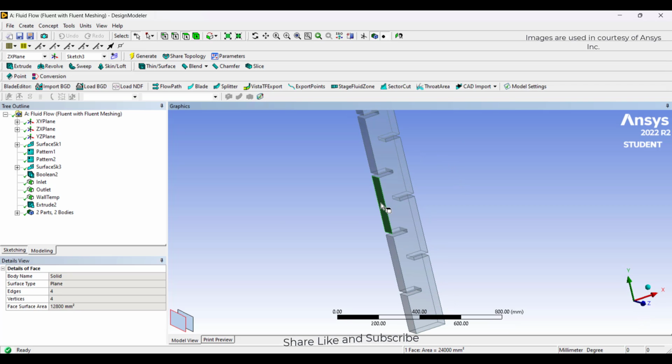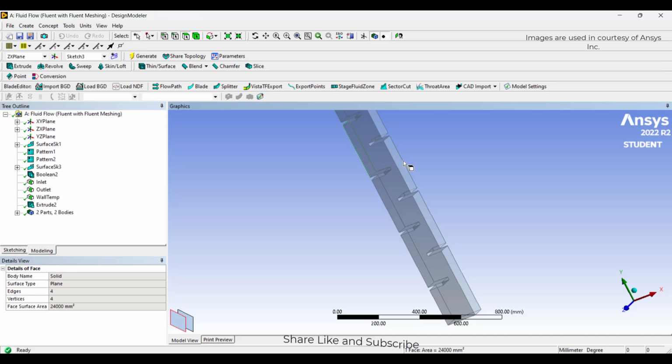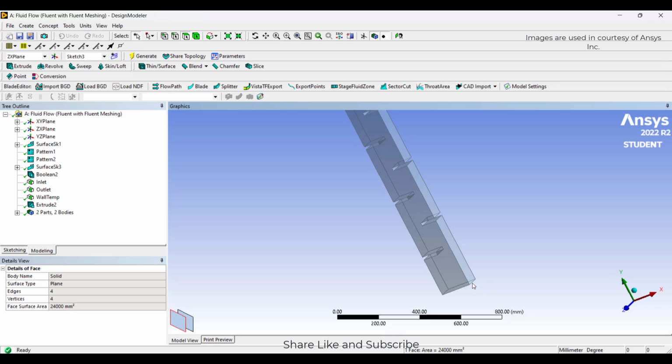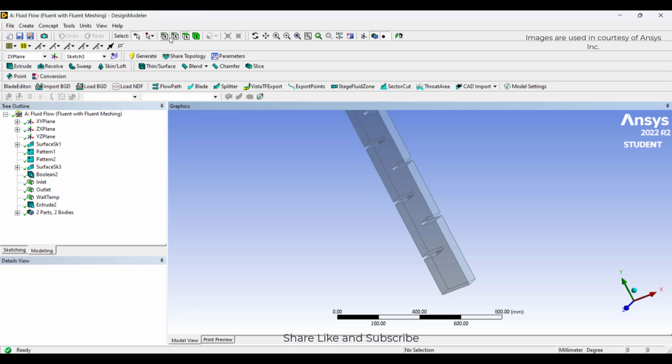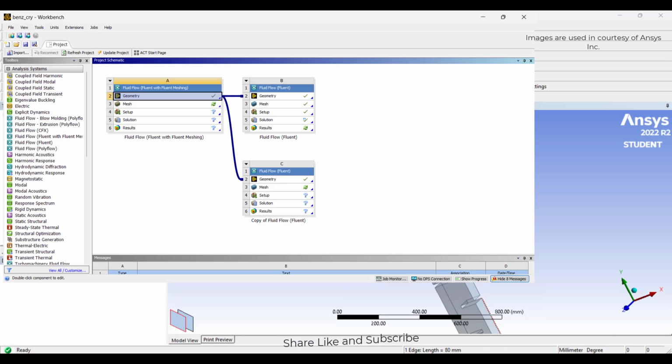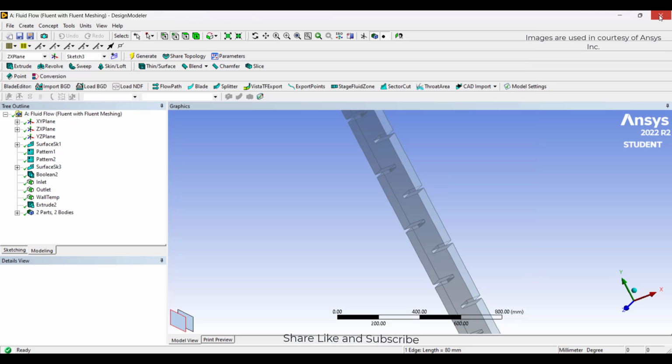And the temperature gradient is given along these walls in a linear way, such that the temperature varies from 285 to 250 Kelvin up to this line. So from here it is 285, from this line to 250 Kelvin at this line, through the profile. Okay, I'll show you the profile also, how I've given it in the Ansys Fluent UDF. But before that, I'll try to mesh this.